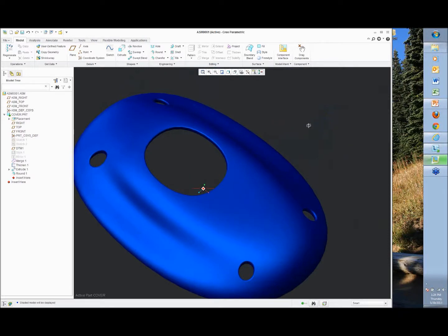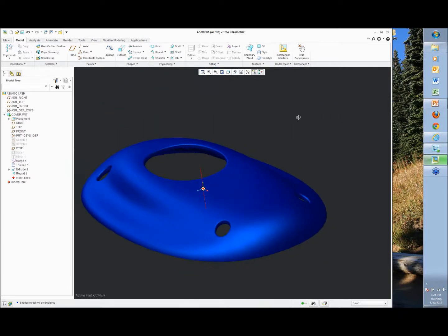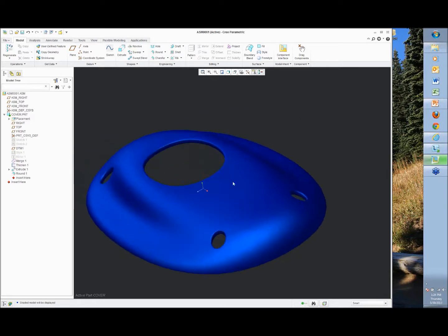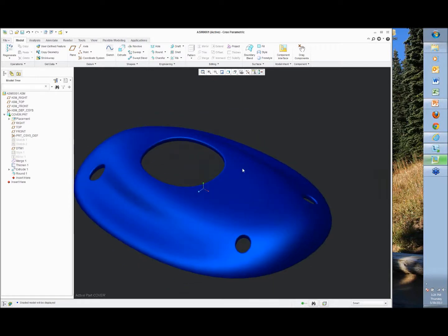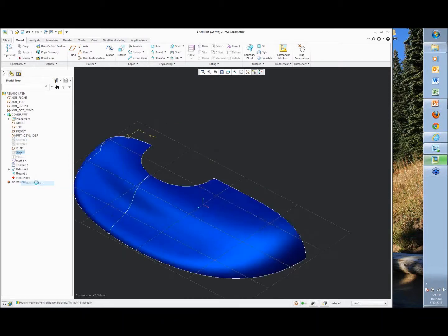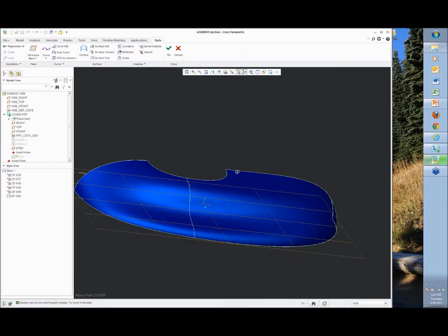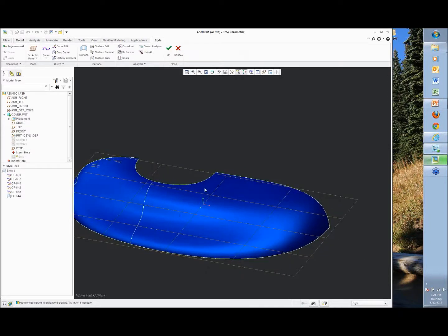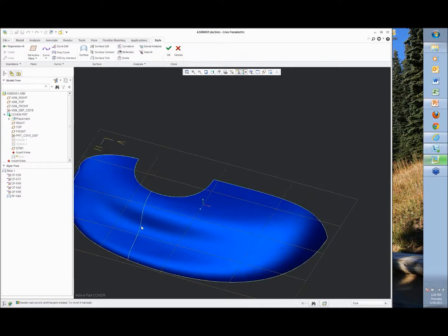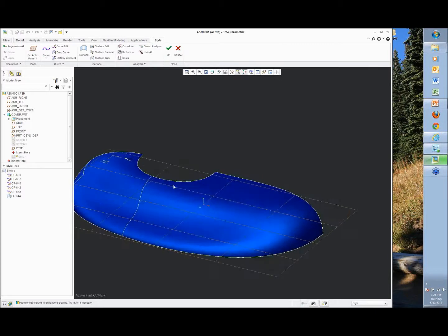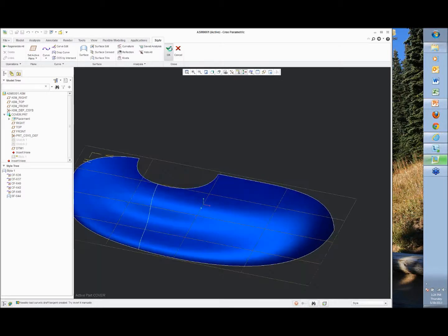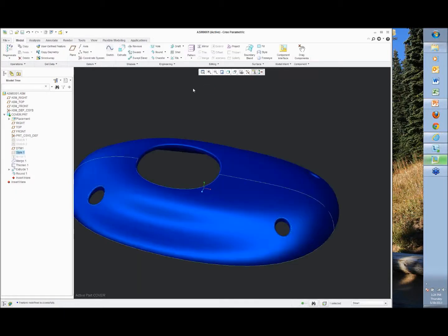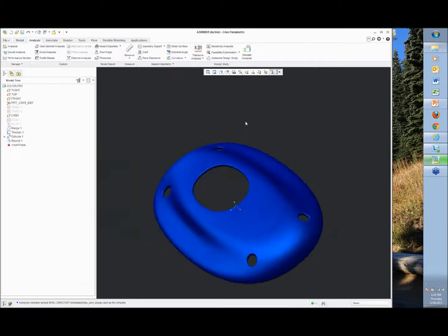That's the first example right there of just taking a model and going from the design from the beginning to the end and building on to what I'm doing. And again, I didn't make it overly complicated. I made a pretty simple deal where I just have a couple of simple curves. If I wanted to add more curves in here, I could add them as ribs, basically, for more control points. A lot of control inside that feature. Right? First example.